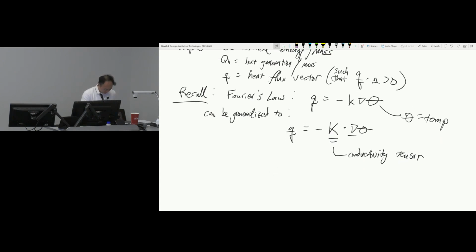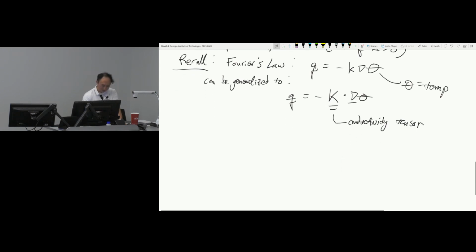Okay, so we've got one term on the left, which is the time rate of change of kinetic energy, and then 3 terms on the right. The rate of work done across the surface by body and surface forces. That's like gravity. That's like a fluid flowing in, bringing in new kinetic energy. And then we've got heat flux, which is different because heat is a transfer of energy. It's not the transfer of matter. So we had to keep those separate. And then you also have any kind of internal heat generation, which is if your thing's on fire or something like that. So let's write all these terms mathematically.